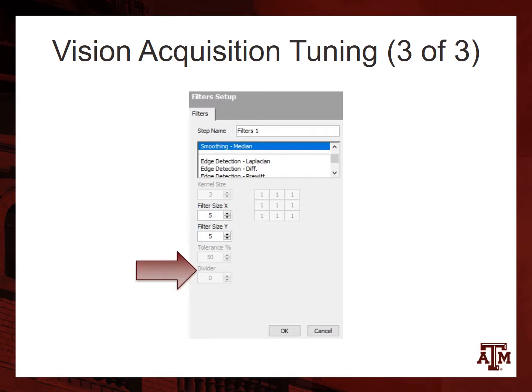The smoothing median filter was instrumental in filtering out small particles, which would lead to errors in locating the orange pylon. However, increasing the filter size values limits the effective distance since the orange pylon would effectively become a small particle to be filtered out at a farther distance sooner.